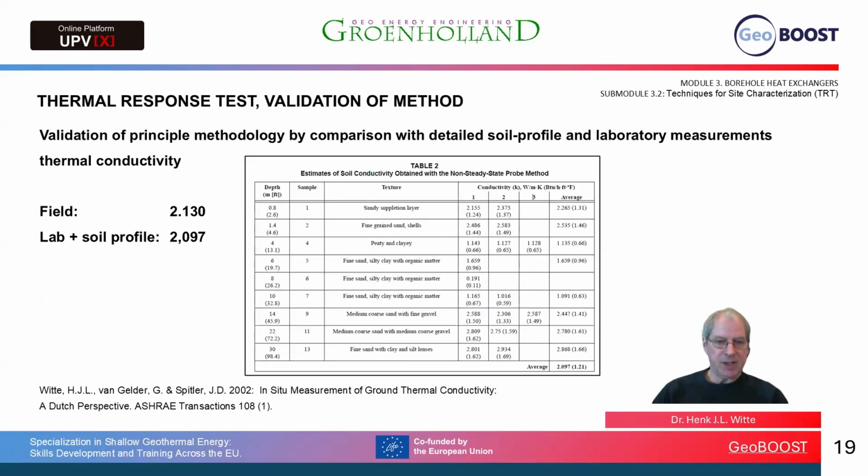The validation of the method has been carried out. For instance, in 2002, we published a test result where we had very detailed data on the soil profile. We had samples of the soil profile which could be tested in the laboratory, and we did a thermal response test on the same borehole, compared the values that we obtained from the laboratory with the values from the field, and you can see that they were very close together. The field value 2.13 and the lab and soil profile 2.097.